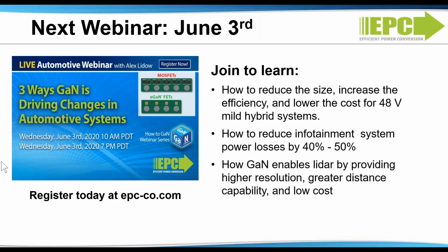Which digital controller does EPC recommend and why? There are a lot of them. The one that we use is the Microchip dsPIC33CK64MP103T. These dsPIC33 series are used in most of our designs. They're really small, 5x5 millimeter packages with 36 pins, and are very cost effective. So we've gotten used to programming them and they work very well.